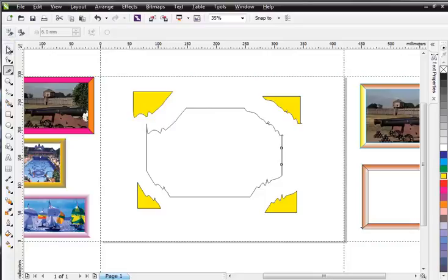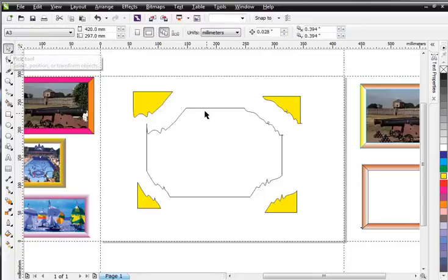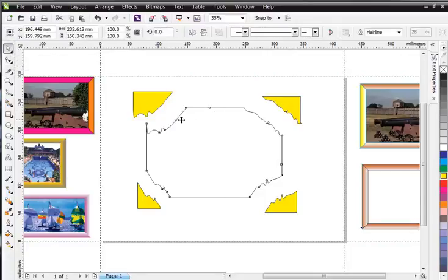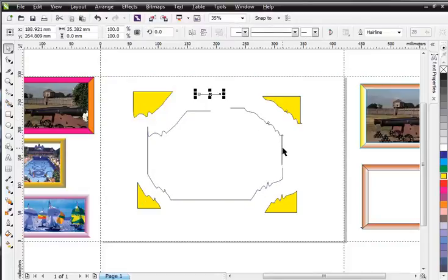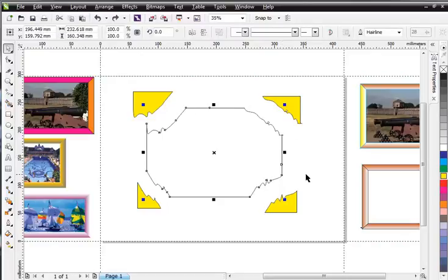Since the first icon isn't active as well, we can now move these cut parts without ungrouping them. Switch to Pick tool and click on a side to deselect. We can now move each of these parts separately. They are now separate paths. Press Ctrl Z several times to undo the changes.